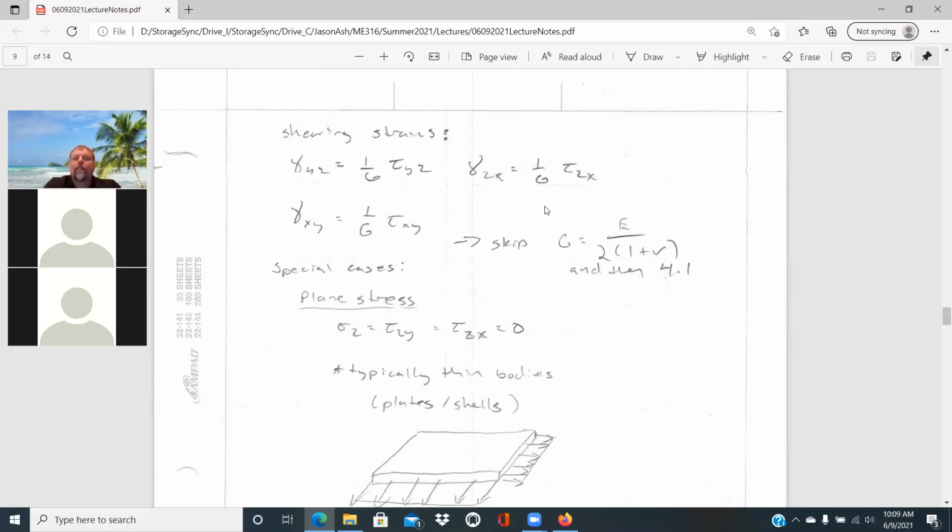So they're just directly tied to one another. In this process, we've really defined 3 material properties: the Young's modulus, the shear modulus, and the Poisson's ratio. But only 2 of those are actually independent. If you know 2 of them, you can solve the third.